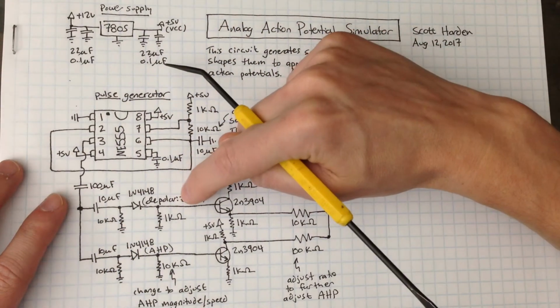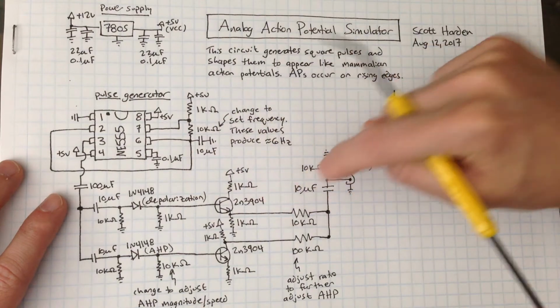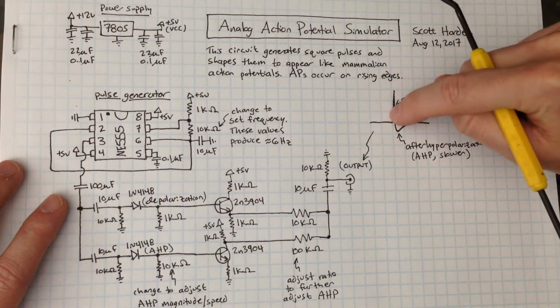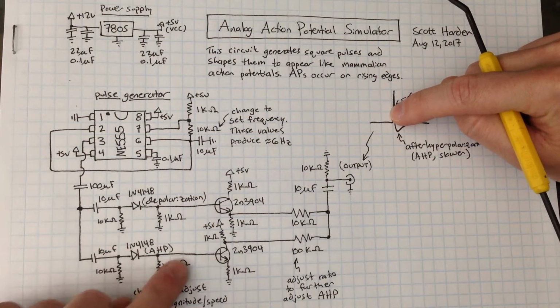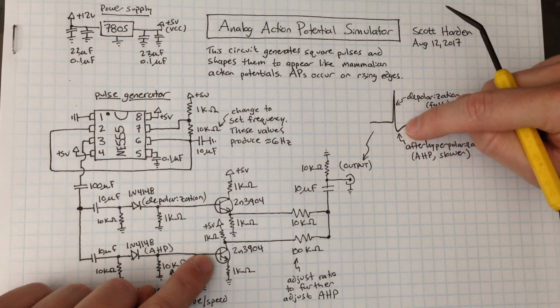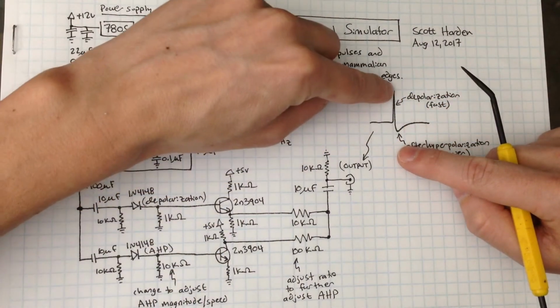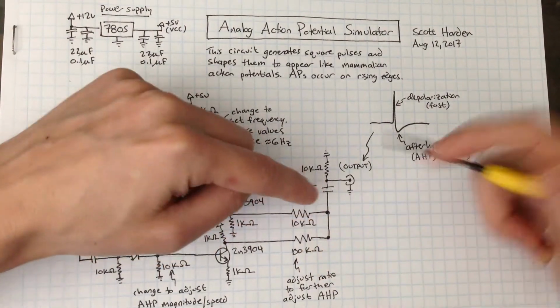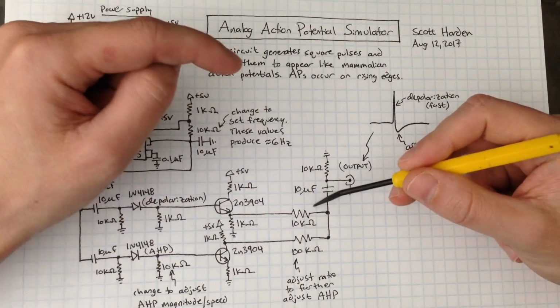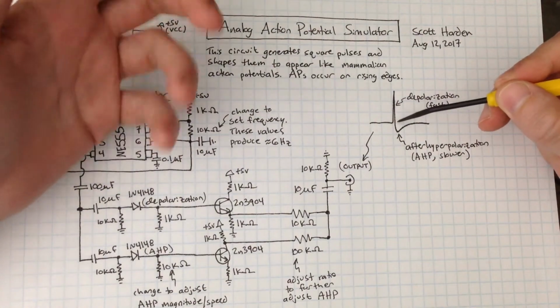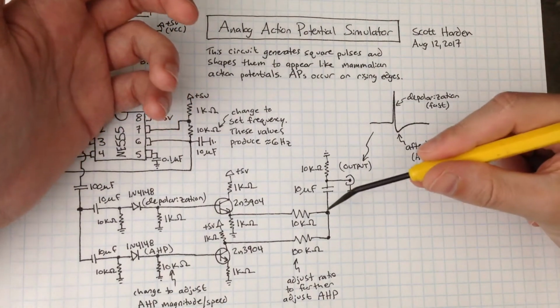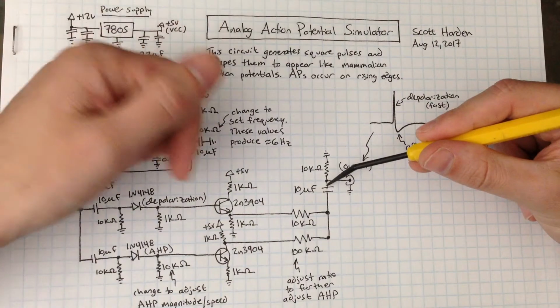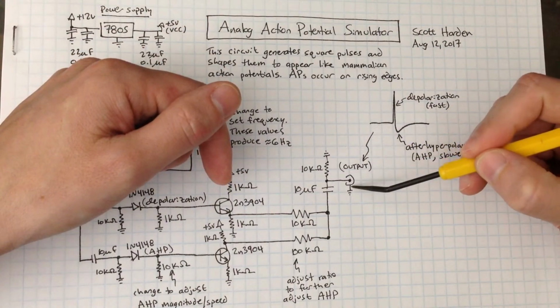And this signal generates a faster pulse, which gets turned into the positive pulse. This lower one generates a slower pulse, which is turned into the negative pulse. And we mix the positive and the negative pulse here with a resistor divider, and the difference in the resistances means that our positive pulse will be more profound than our negative pulse. We mix them here, decouple finally with one series capacitor, and then we take the output here.